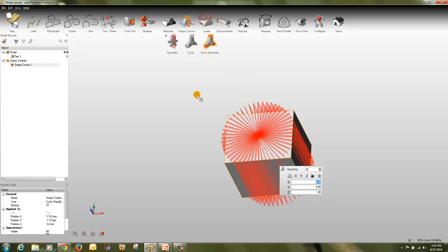Then cyclic symmetry. It will repeat the same pattern from 1, 2, 3, 4, but it will have the symmetry, like whatever is here is the same as this. So it will have the repetition with the symmetry. This option will help us with cyclic repetition with symmetry, as it is showing. And this one will only have the cyclic repetition, meaning it will have the same division across, the same amount of material removed in each repetition, but the symmetry will be the same along this.